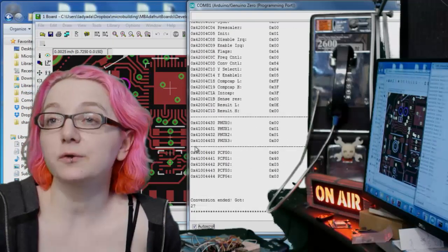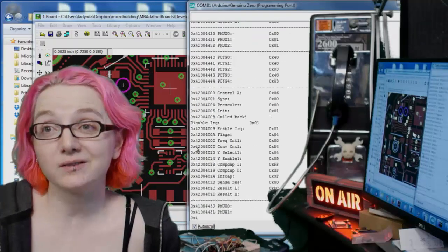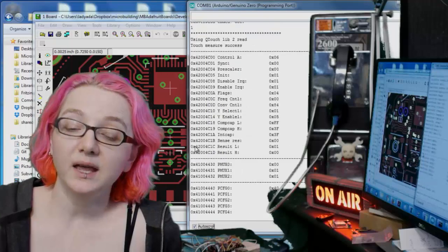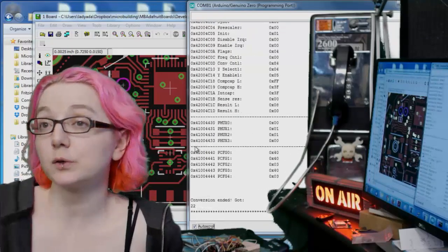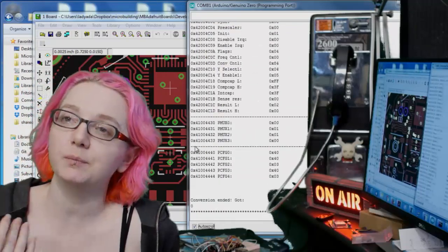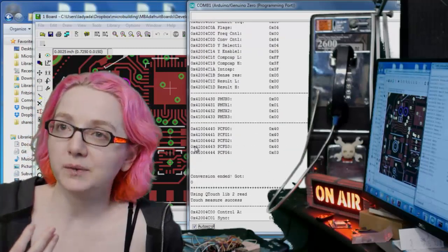Is the IR used to measure distance? You can use IR for 2 things. You can measure distance with it by looking at the DC value. But with the AC value, you can use it as a remote control or remote control receiver, or communicate between Circuit Playgrounds. So they can have a very basic data transmission protocol.